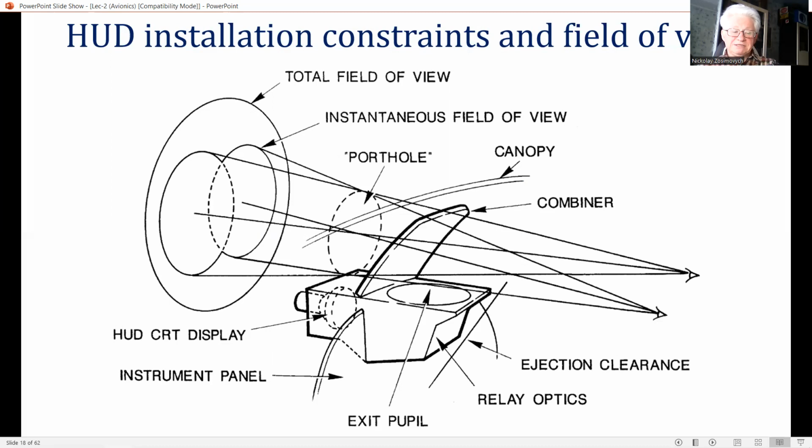By cockpit space constraints and practical considerations, large lenses are very heavy and liable to break under thermal shock. The HUD combiner occupies the prime cockpit location, right in the center of the pilot's forward line of view and the top of the glare shield. The size of the combiner is determined by the desired FOV and the cockpit geometry, especially the pilot's seating position.